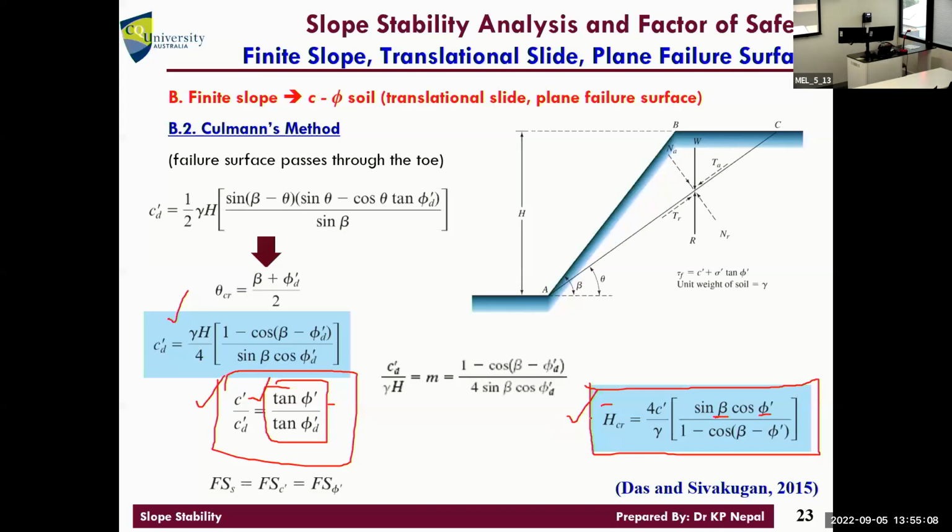When you get that, put it in this equation now. Hcr is 1.8. Can you write that? Just put these values in, and what you need to find is tan phi D, the developed value of this. Can you calculate that? Which one is quicker, to calculate phi D, that or that?